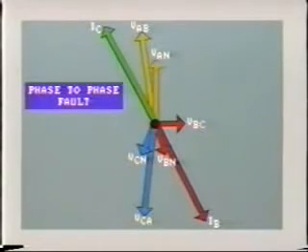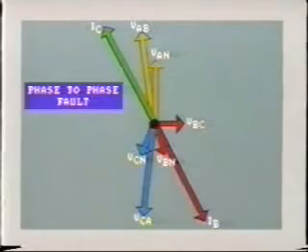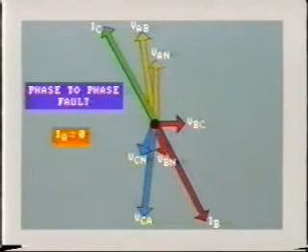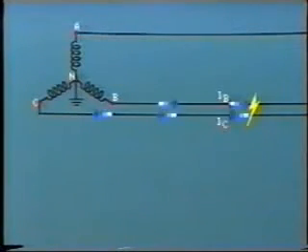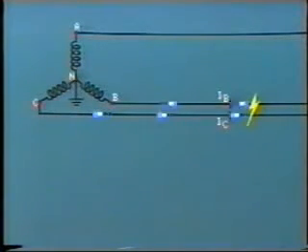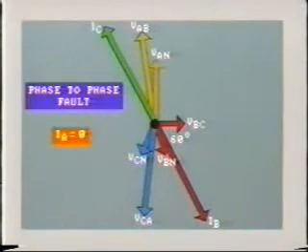Now let's look at the line currents. As we are considering zero load, IA is 0. The current traveling through line B is feeding the fault, and this will lag by approximately 60 degrees on voltage VBC. Once IB passes through the short circuit, it returns along line C. So current IC can be shown at the same magnitude, but 180 degrees apart from IB.